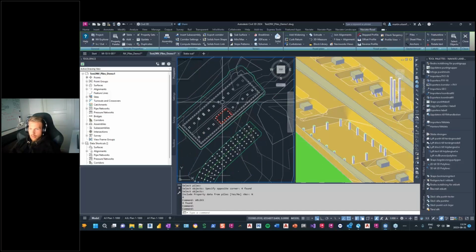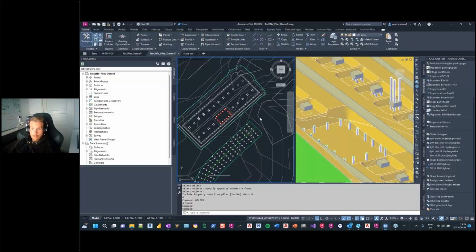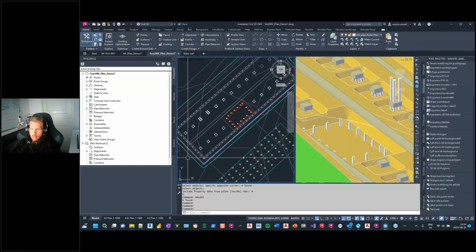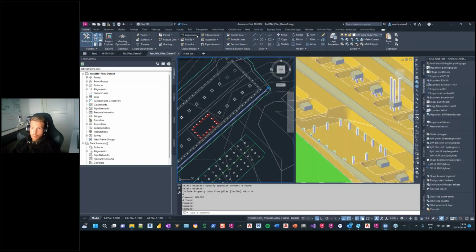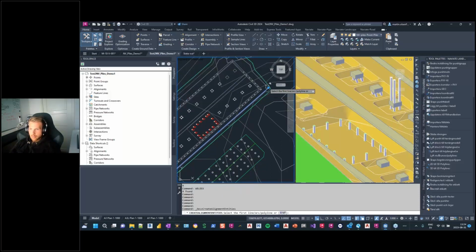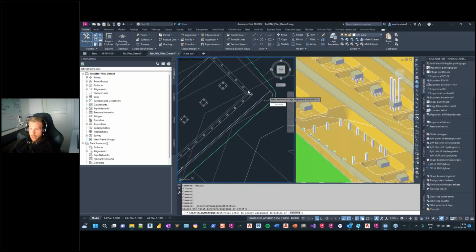And we got some different ways to create sheet piles. I can use alignment, I can use a feature line, I can use a 3D polyline. In this case, I will use alignment. And I got a prepared regular 2D polyline here. So I will just create my alignment from that polyline by create alignments from object. Choose this alignment